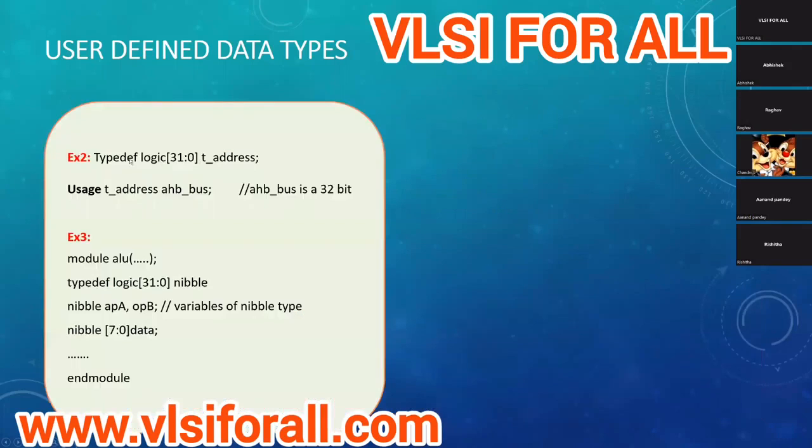For example, there's a typedef logic 31 down to 0 t_address. Let's say there's a design where address is always 32 bits. Why would you keep writing logic 31 down to 0? You'll just typedef logic 31 down to 0 somewhere at the start of the module, and then use this t_address wherever you are declaring a 32-bit signal. Now let's say there's a design change, and 31 is changed to 63. You can just change it to 63 here, and it gets changed everywhere, right?